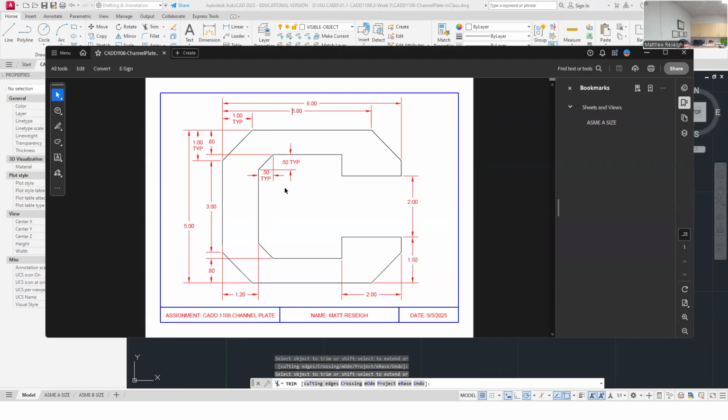However, the inside ones are kind of a different grouping. And so these are half-inch typical chamfers, and only here and here. So this is definitely kind of a lazy drawing, in that it's not maybe up to ASME standards, and maybe I could use some better terminology to be more descriptive and less vague when I go to finish dimensioning it, which we're not doing yet, but it's just something I'm considering.